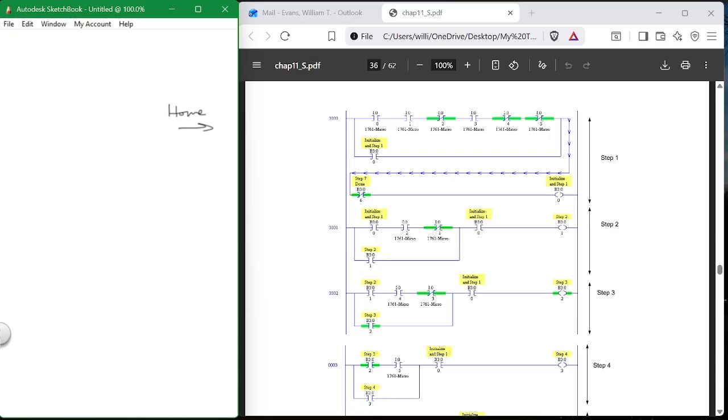So this bit is the first bit that turns on. It says this is your run bit. It turns on immediately when you're running, and it stays on. Then this bit turns on. This would be step 1. Then after it's done, it's step 2. So what are you doing? You're sealing these circuits as you go down, step by step by step. This turns on, then this turns on, then this turns on, and they all turn off.